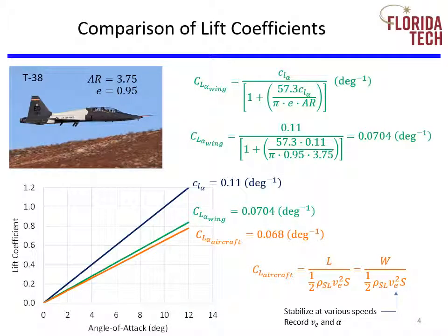Practically speaking, in order to calculate an aircraft lift coefficient, there are three approaches which can be used depending on the known conditions of the problem. First, you can calculate it directly using the equations above. However, equivalent airspeed and weight must be known.